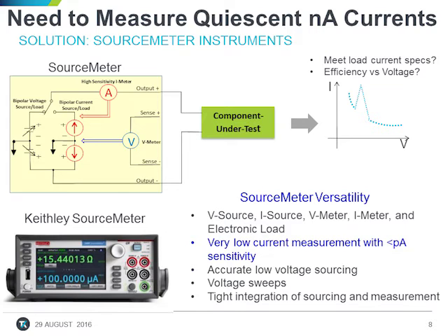For those components that are critical to your design, you may want to characterize their performance. What is the current draw at the voltage you will be using? How does the current draw change as your battery voltage decreases? Is there a range of voltages where the efficiency decreases significantly? This can be the case when a component is operating at the low end of its specified operating range. A component may behave as shown in the IV plot in the upper right.